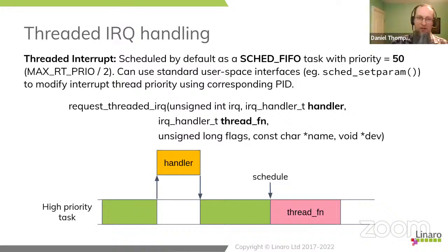Because we're going to go and read a couple of registers to read our sensors, we're going to set the results that the controller gives us, and then we're going to go back to sleep. And if what we want to do is control that process, and controlling that process is the most important thing for us to do, we don't need to take interrupts while waiting for it. So that's the reason I put high priority for those and then drop down to a very small number like 40, is to split either side of the default interrupts.